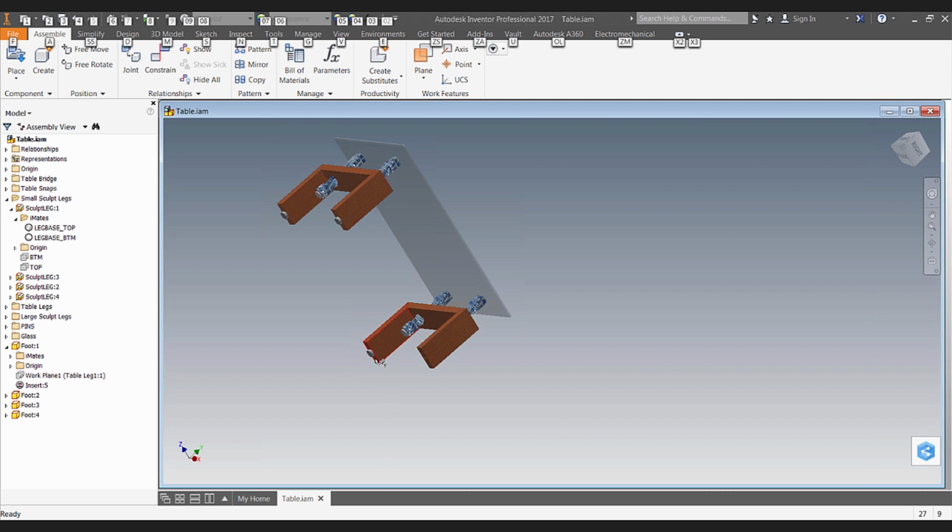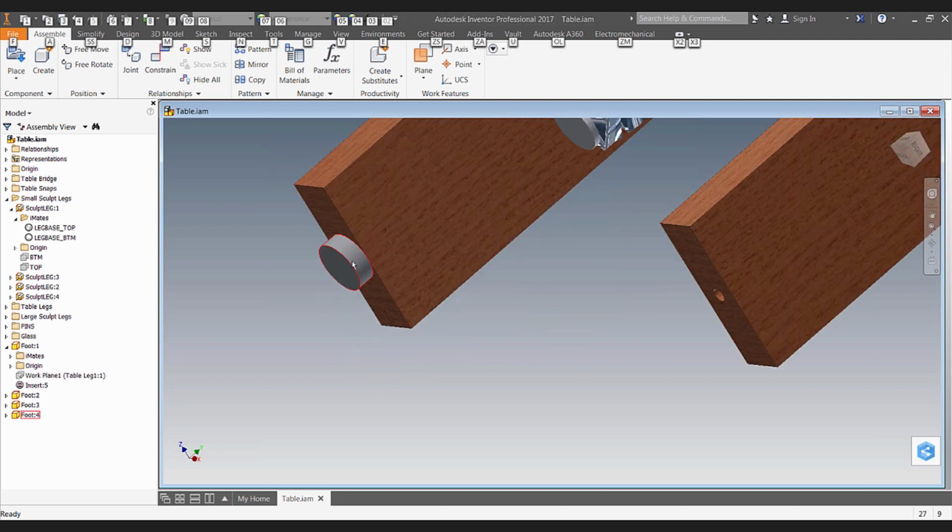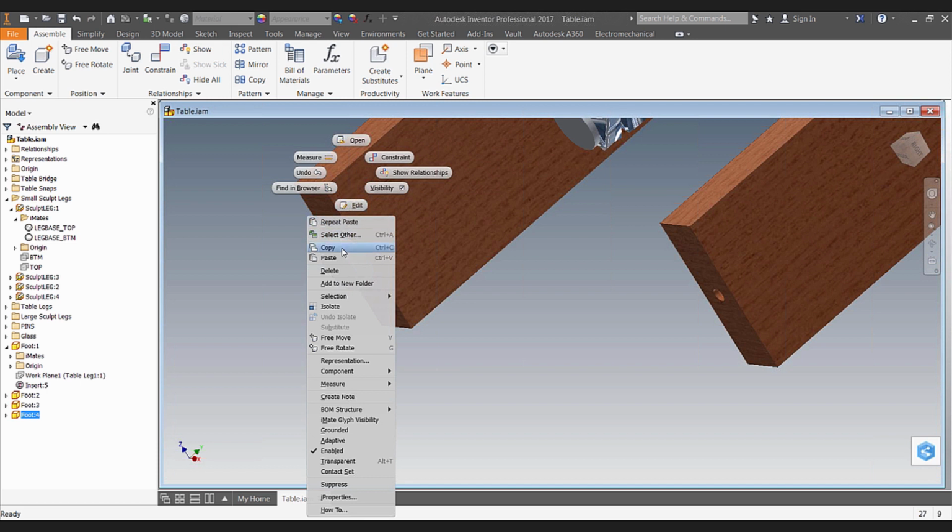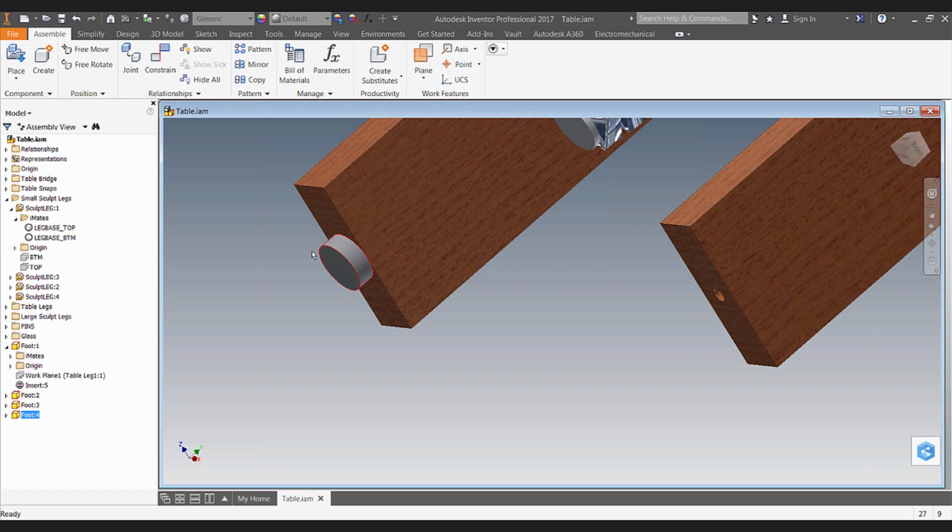The other thing, real quick, I know we're kind of running up against our time. I do want to get into the Q&A session, but the other thing that you can do is, if you already have a part inside of your model that has an iMate, but you didn't apply it, and you don't necessarily want to drag it, you can go back to that same menu that we were looking at and tell it to go ahead and automatically apply these iMates.